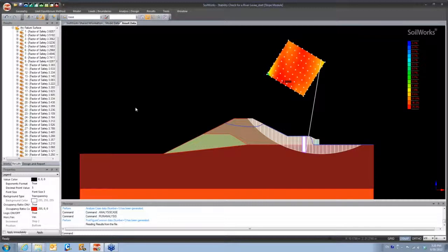Oh, absolutely. In the ground module, which is the module typically used for that type of application, there's a construction stage analysis feature where you can model this. Like you said, embankments are typically built sequentially, with layers stacked on top of each other. What I can do is show you a construction stage analysis that will take that sequence into account.